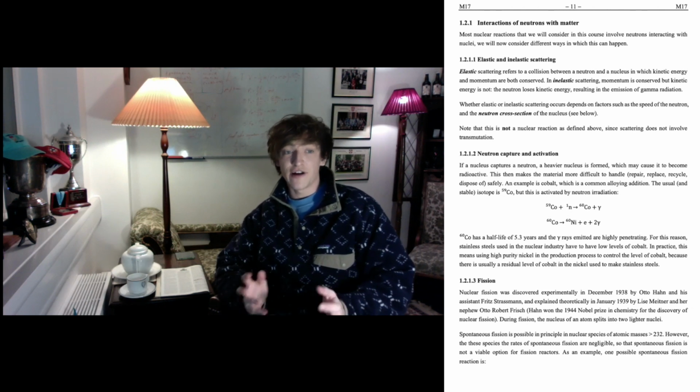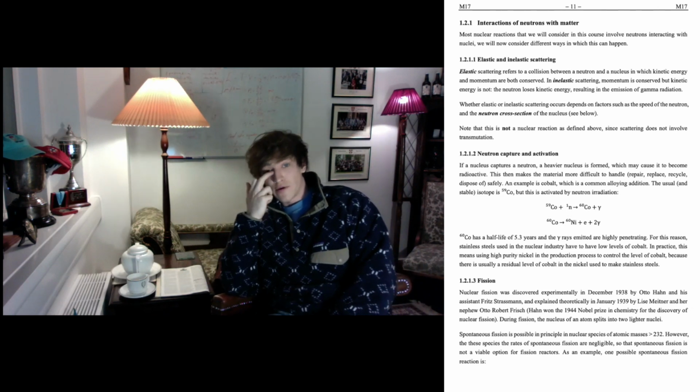And as such, nuclear alloys have purposefully very low levels of cobalt, as cobalt is typically present in natural nickel deposits. Any stainless steel used in the nuclear industry doesn't just use natural nickel deposits, it has to use highly enriched or high purity nickel to avoid any cobalt contamination, because you don't want this cobalt-60 emitting gamma rays and harming your people working, your personnel on your power plant. So that's neutrons leading to activation.